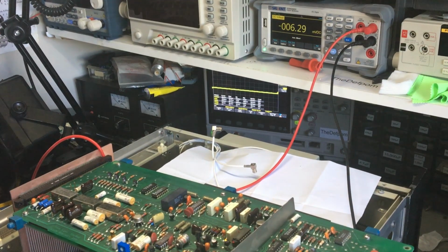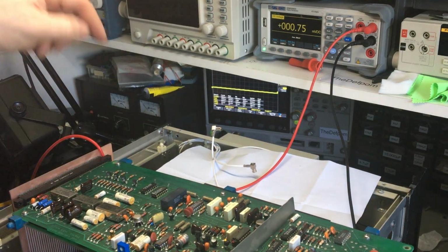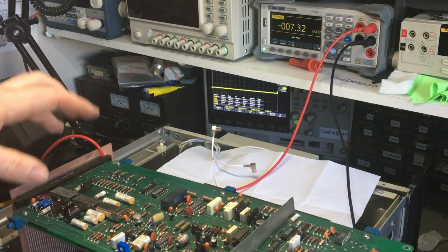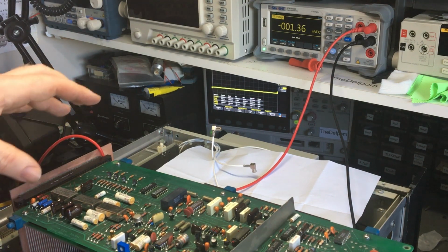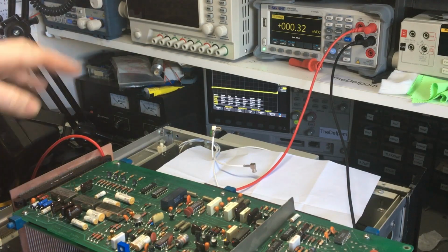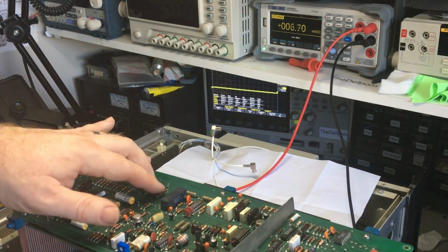Okay, I've found an explanation for that difference. Pin 4 is the 1 MHz output, and that just feeds straight out, whereas all the other pins are linked to the relays. So they're actually getting a pull-up voltage fed back through the coils of the relays. So that explains why there's a difference here. So those two chips are absolutely fine.